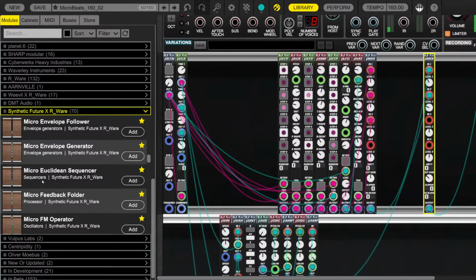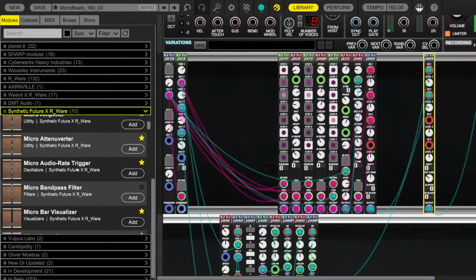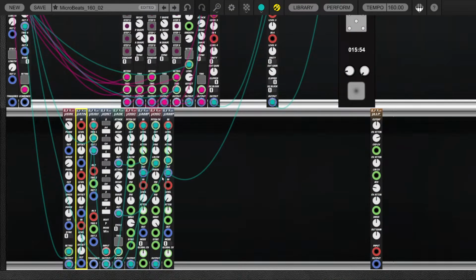Because these sine LFOs, they're in the range between -5 and +5 volt. And 1 volt is 1 octave. So we're going between -5 octave to +5. That's LFO territory to very high. And all we need to do is attenuate it.